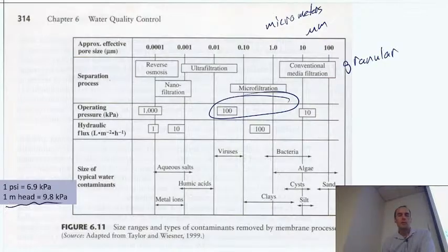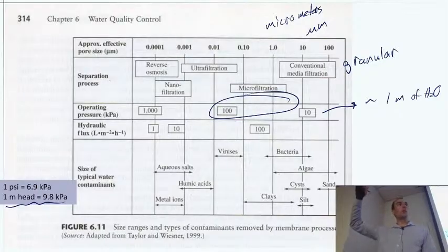So this means that approximately 1 meter of water stacked up on top of the granular filter works. But maybe if that resistance doubles as we operate and it gets dirty, maybe it becomes 2 meters. So if you think back to those videos we saw of the water stacking up on top of these granular beds, that kind of tracks, right?